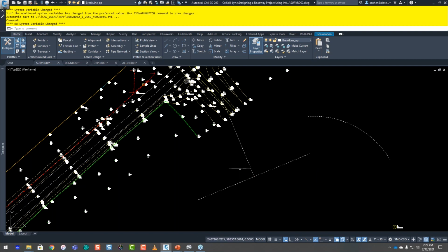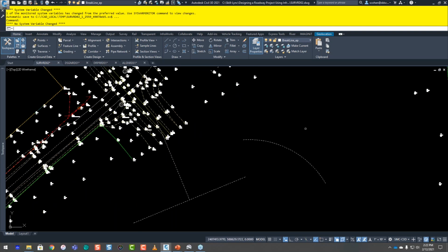So I use that command almost day in and day out. So it's a very useful command. And again, it works with arcs as well. So I can pick any point on this arc. So let's say I've got a specific point from here. There's a driveway, there's some sort of intersection that I need to actually do something with from this arc. So I click there. What's my distance? If I want to go left, just so you know, I type -50. Or right, it depends on which way it was drawn. Or I can go the opposite way. So I began this way, so that was left, that was right, right? So just do negative if you want to go the opposite direction. But that is a crazy useful tool. I actually love that tool.